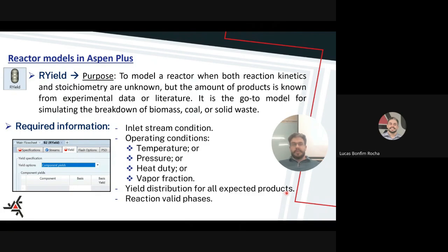For example, for producing biogas, I can specify the composition of my biomass in terms of proximate analysis and ultimate analysis. Based on the characterization, we can try to specify how much methane is produced, or how much carbon dioxide, methane, and other compounds I have in the biogas. And it will try to estimate how much of the mass fed into the reactor is converted to biogas and how much is converted to the digestate or the other co-products from that system.